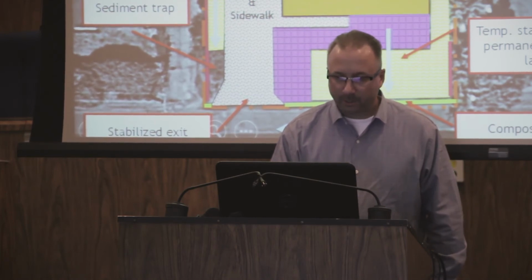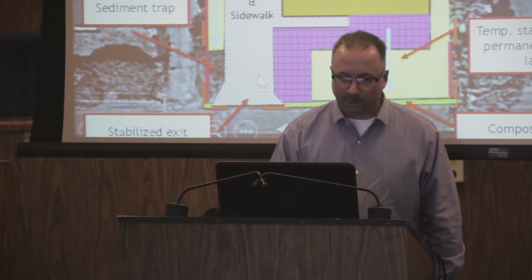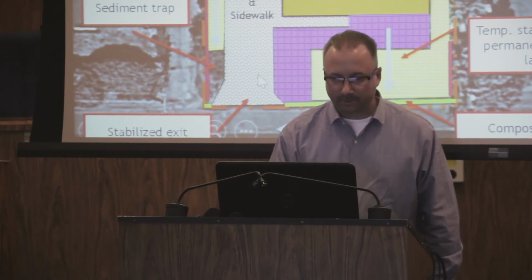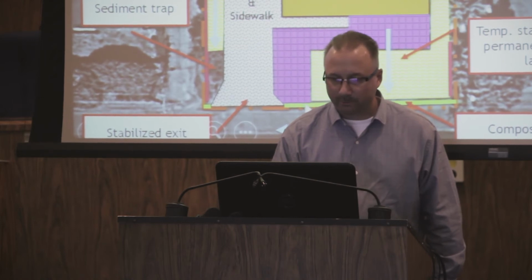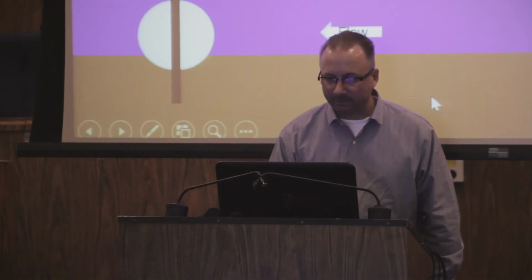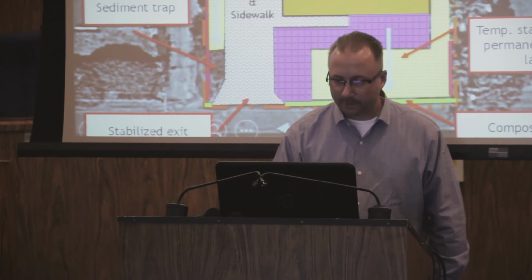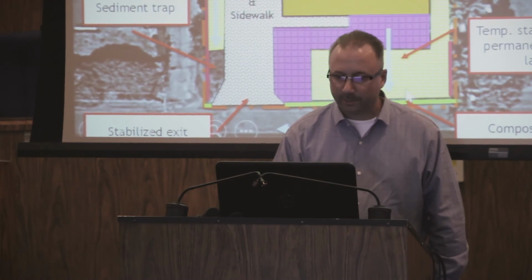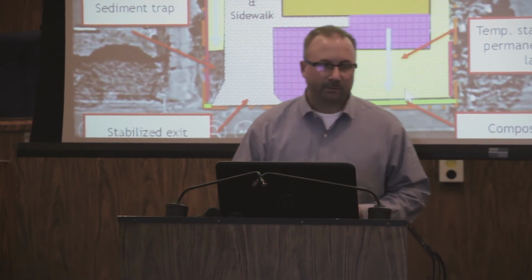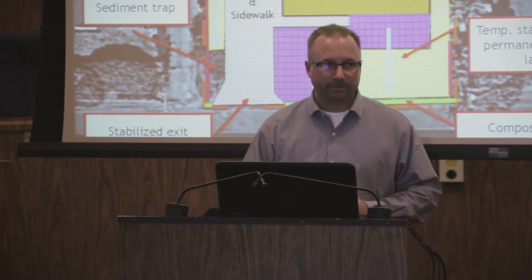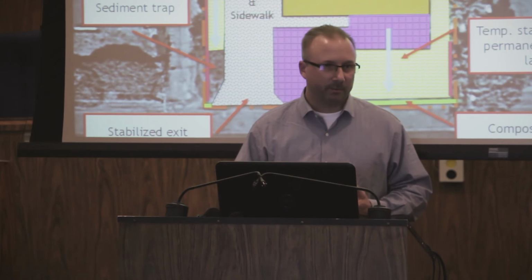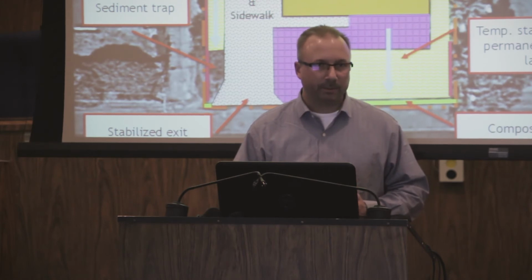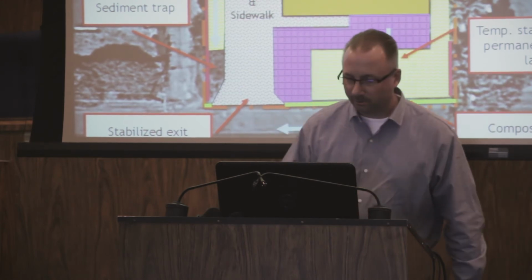Our other sediment controls, as I mentioned, are the driveway itself. That's our stabilized entrance. And then our compost sock I put along the perimeter at the base of the street. Right here, and then a little piece right here. The reason we did that is because that's where water is going to flow off the site, and we're going to filter that water as it leaves the site. We're not trying to impound any water or leave any water on site. It does a good job of filtering.